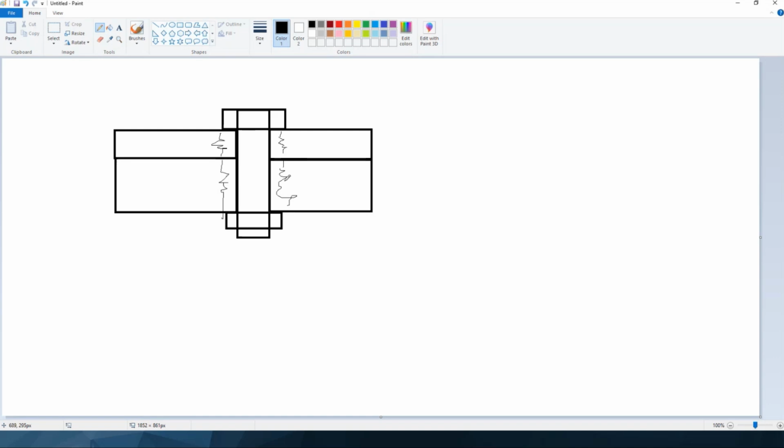Okay, so sorry, that last one is really badly done. So compressing that plate, I'm acting against that stiffness that represents the stiffness of the plate. So effectively the thickness, the elastic moduli, and the area over which I apply that. All of that I can simplify as a single spring element.